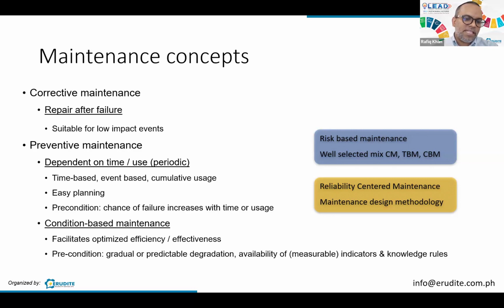You also have the effectiveness of every practice when you do the maintenance improve. So you don't want to have a faulty part and then you do the replacement. But if it's aging well enough, you think it's a good time to do it, you can already make a decision. So there is also again a precondition. You need to have a gradual or predictive degradation.